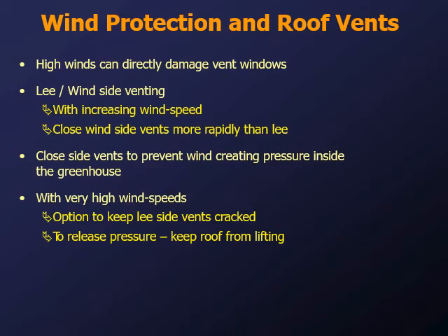Typically, it is important to open the leeward side to reduce pressure. You can have situations where if all the vents are closed and a real storm blows in, the outside pressure from the greenhouse can drop dramatically, and the pressure difference can be enough that you can actually crack some windows. So just be aware of that. Lots to think about when you're operating a greenhouse.